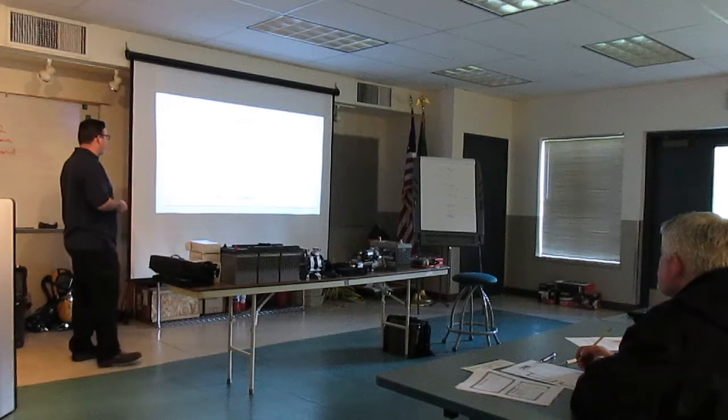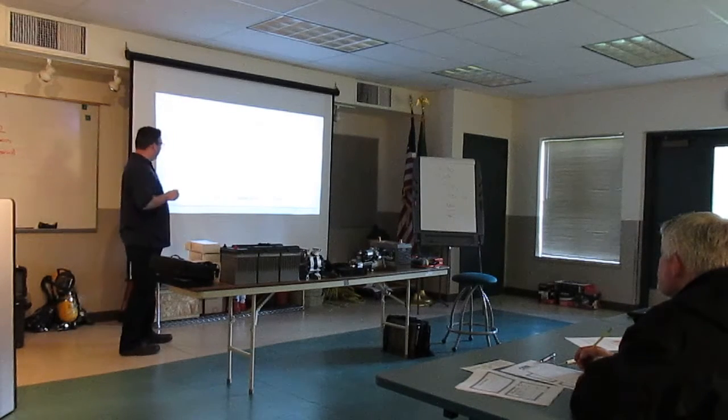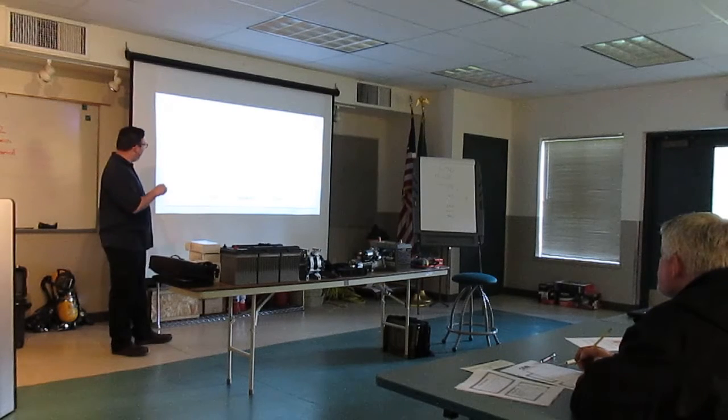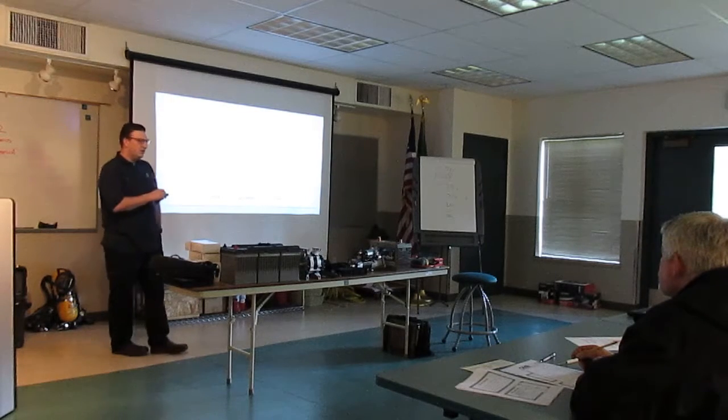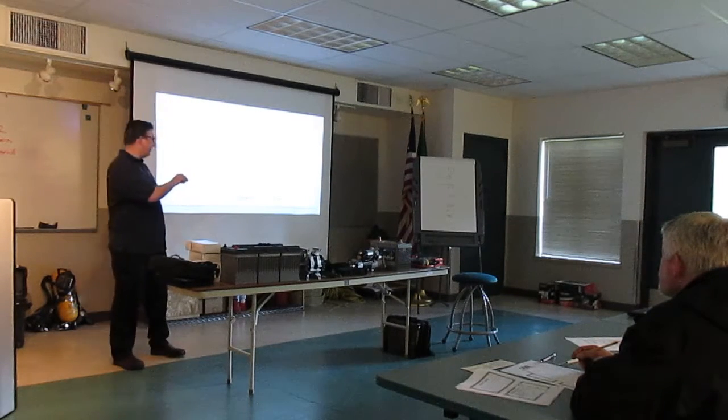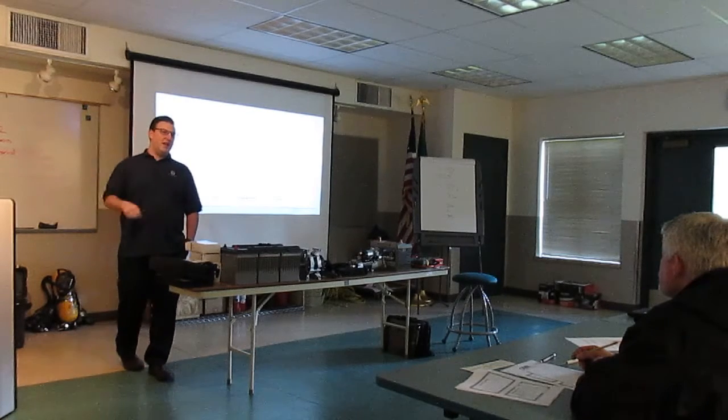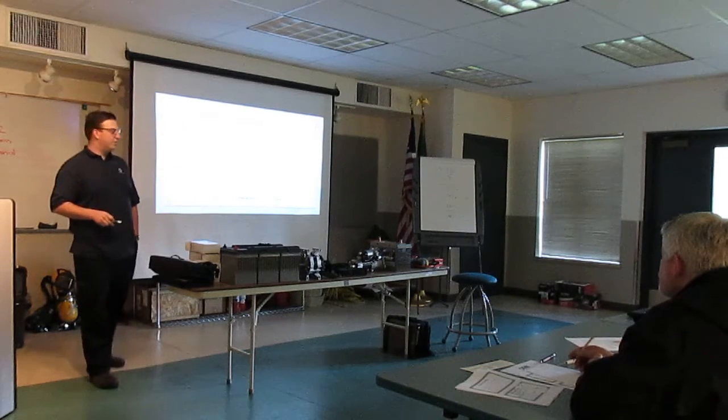On a 3-stage automatic charging profile, things get changed a little bit. Now we have a charging system that will charge between 13 and jump up to 14.5 during the high point in which the system needs the most current. As the current drops, the voltage settles out. And then once it sees that the current has dropped enough, our charging drops the voltage down, because you only need a certain amount of voltage to trickle those batteries as you're going through with them.